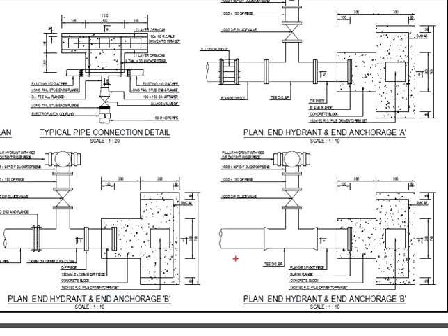Let's say you are proposing the pipes with the spigot joint. You have to consider how you're going to connect with the other fittings if they are made of flange joint. If you provide fittings in the spigot joint also, that shouldn't be a problem. But if you are proposing otherwise, you have to come up with a mechanism to join them. This is one of the lesson points that you can gain through the drawing here.